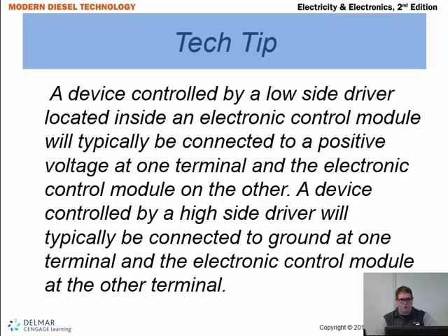All right, here's your tech tip. A device controlled by a low side driver located inside the electronic control module will typically be connected to a positive voltage at one terminal and the electronic control module at the other. And that's how we know. Remember, when we're looking at a schematic, we have to find that path from positive to negative. So if we are looking at this device and we find our fuse is at the top, we go down, we find the component, and then lower down in the schematic we find the ECM or a module, then we know that that's a low side driver.